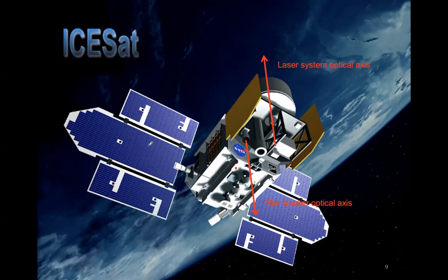And usually what you need is to report everything to the center of mass, in order to integrate the center of mass position of the spacecraft. But in terms of attitude, what really matters is the orientation of the reference frame. So what we want to do is to reconstruct the orientation rather than the position.